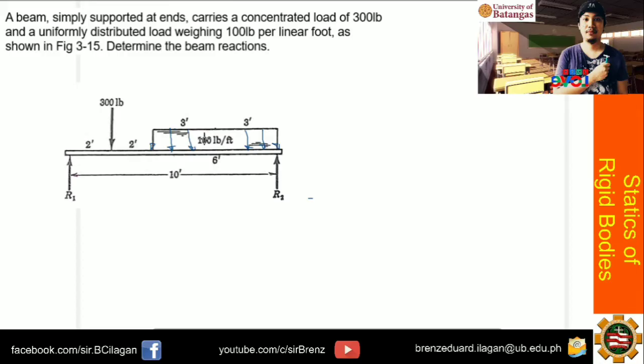So what you do is multiply the 100 by the total span. So this can be replaced as a concentrated load acting at the middle of the 6 feet. So 100 times 6. If you notice, the unit of 100 is pound per foot, and you multiply it by 6 feet, so you are left with pounds. The feet cancel. So, 600 pounds, at a distance of 3 feet away from this support. Or if you want, you can just use the 100 pounds per foot. I think you will still arrive at the same equation if you solve it.